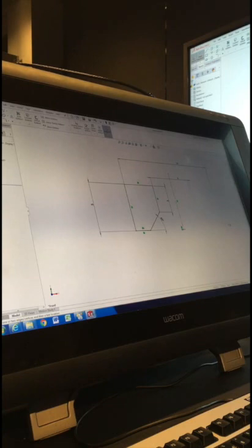There are two issues on yours. The first: remember on that first sketch, we extruded that little line segment, and we've got another one here. Instead, you need that to be lined up. Second, we want this to be horizontal with that point, so it's in line. Also, your dimension is way off. It should be 5. That messes up the shape, but all we have to do is drag. Drag that one around, and then the shape's back. Then you can just add in the other dimensions.